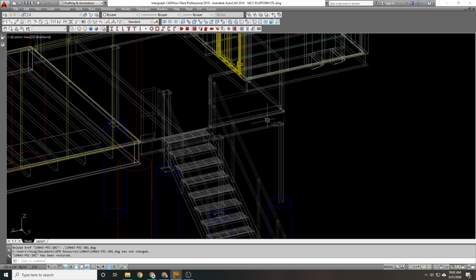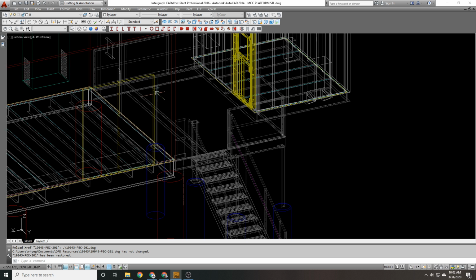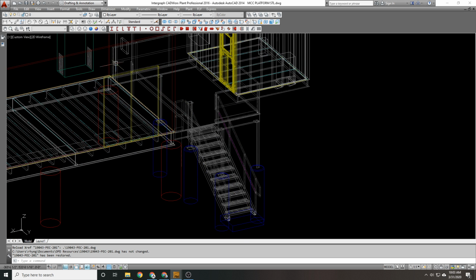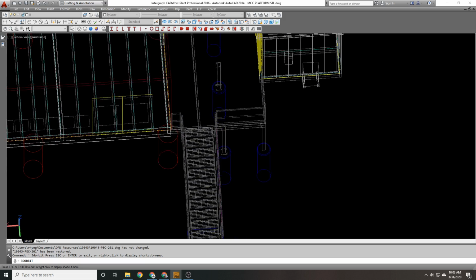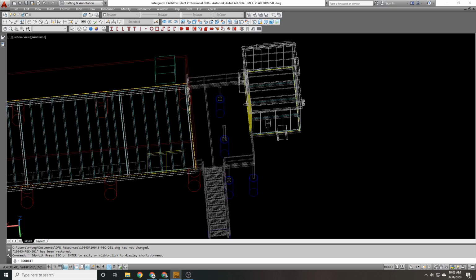There is a temporary structure that was put here. I'm not sure if electrical created this or somebody else. But I'm not going to follow their format. It's just to go by something that they think they need. I'm going to do something very different here. We have foundations for the buildings, so I can't exactly put my columns right on the edges here because the foundations for the columns of my platform will clash with the foundations for these two buildings.